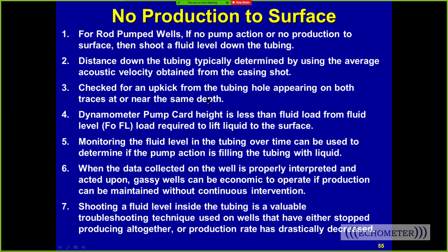And that's what we just said here. They'll be at the same depth. Now, another thing that you need to consider is that if you run a dynamometer card and you have a hole in the tubing, your pump card should be much less than the FO from the fluid level, so you compare your pump card height to the FO from the fluid level.